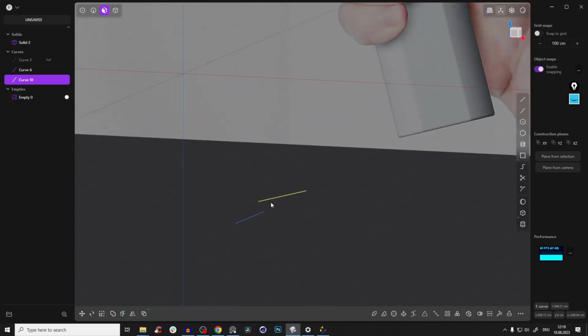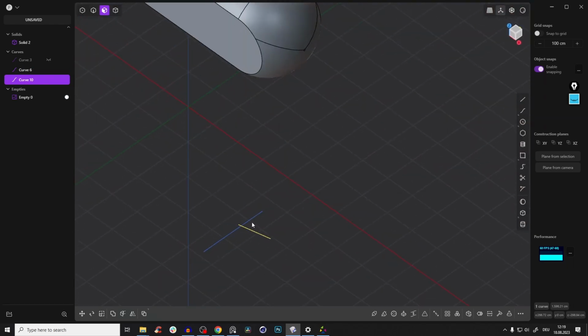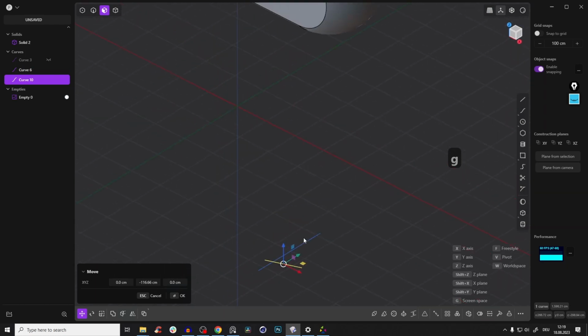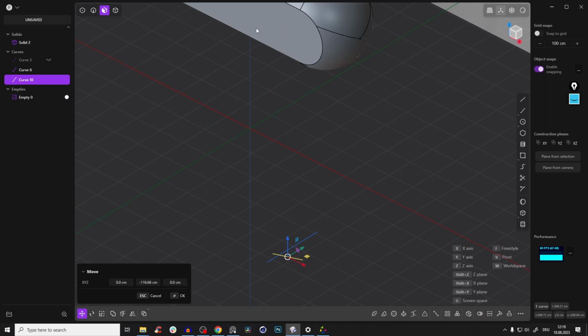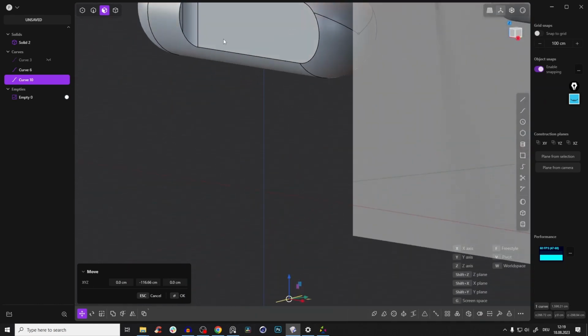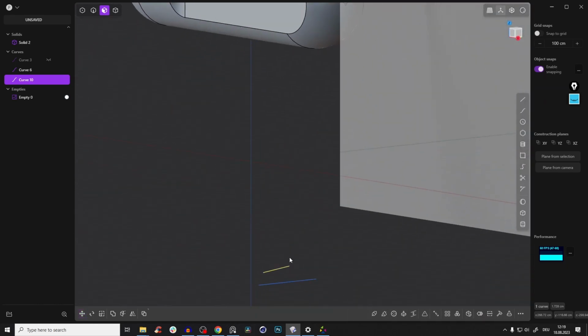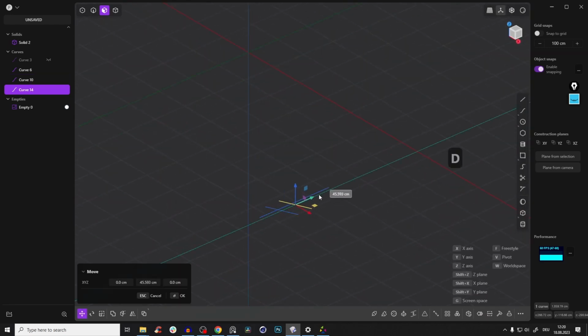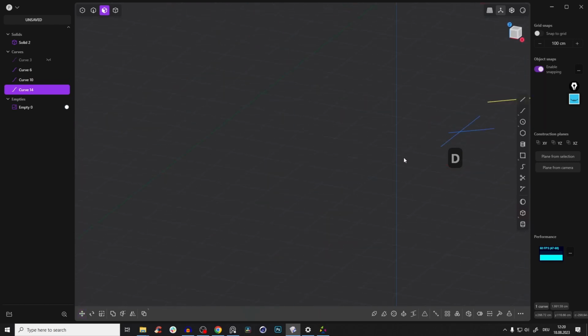And we need two of them, right? So first of all, press G and Control click here to this beginning curve, because this will be our edge. And because this is the same distance or the same thickness, it will perfectly merge into that. So while this line is selected, Shift D and just Control click and snap it to this endpoint. Perfect. So this is exactly what we need.